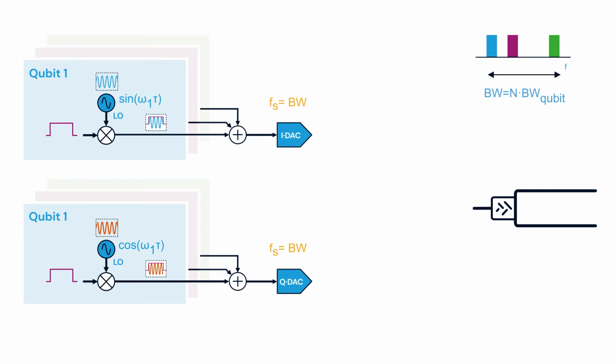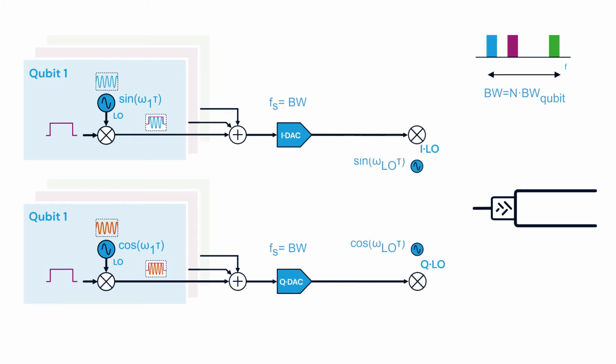We build the in-phase path using the sine and the quadrature path using the cosine, and we sum them up together. In this way, we can generate exactly the same signal as before by proper cancellation of the unwanted signal on the two sides. Now, we only need digital-to-analog converters with a sample rate that is half of the sample rate required in the previous system. In this way, we are much farther from the limits of today's technology, at the cost of doubling the system size and introducing both sine and cosine oscillators, but this can be implemented.